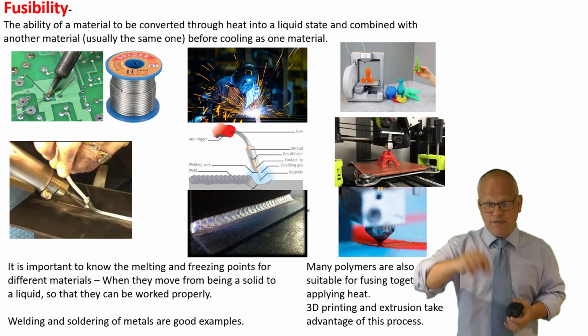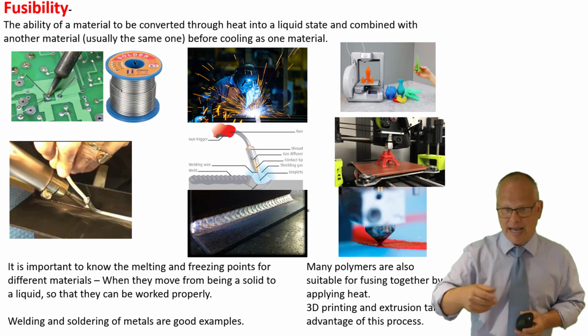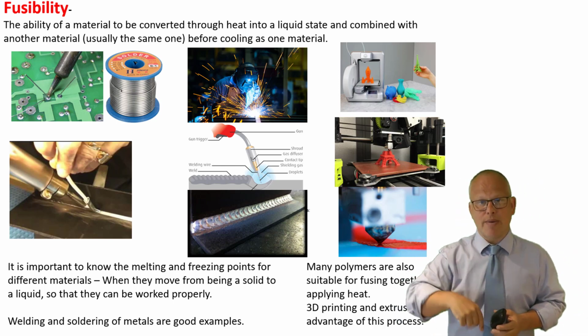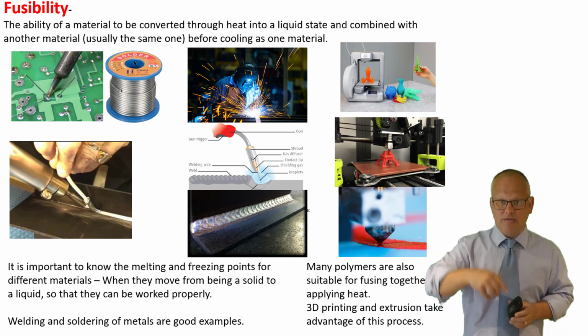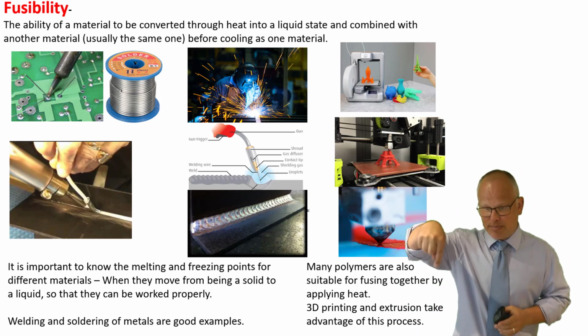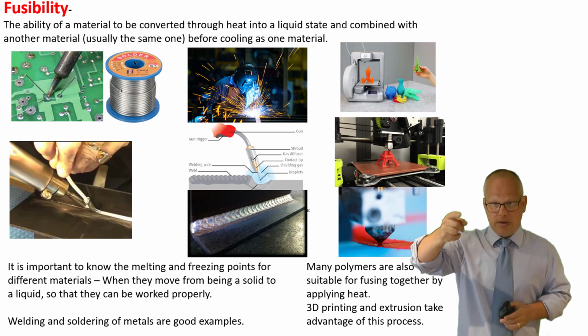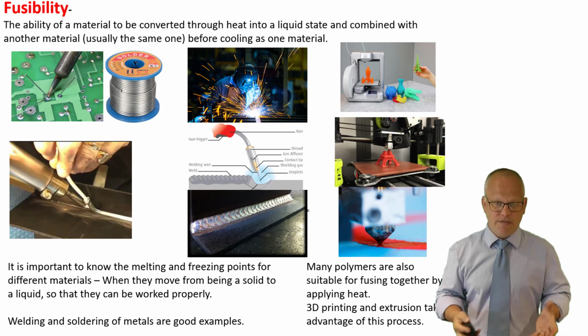So the fusibility of the material, of the polymer, ABS or polylactic acid, is dependent on the temperature being correct and the feed rate being correct. It's worth having a look at some 3D printing to see how each layer is deposited down and it fuses with the layer below it and eventually with the layer above it. Fusibility.